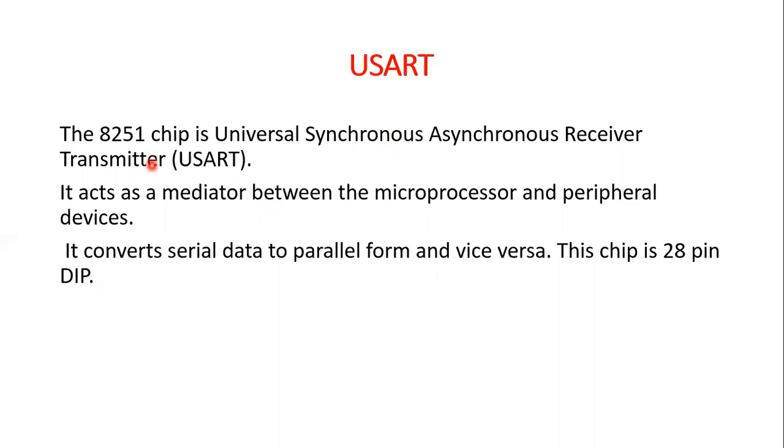The 8251A is a programmable chip designed for synchronous and asynchronous serial data communication, packed in a 28-pin DIP. The 8251A is an enhanced version of the 8251. It acts as a mediator between the microprocessor and peripheral units. It converts serial data to parallel form and vice versa.